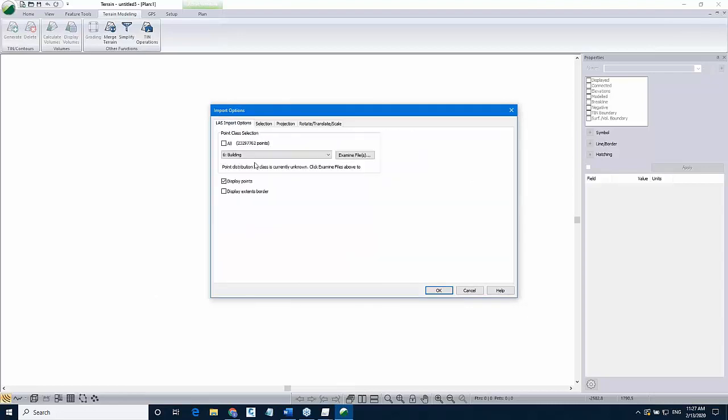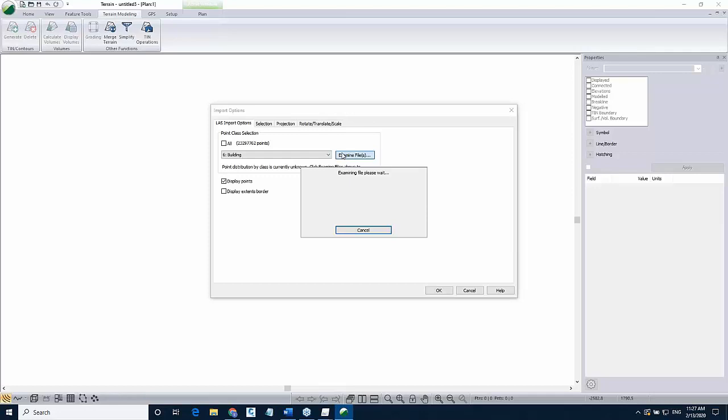This time I'm going to import another layer. We have points on the roads in the reserved layer. This time I want to import these points into the terrain module and then use the georeference image file as a background for that.